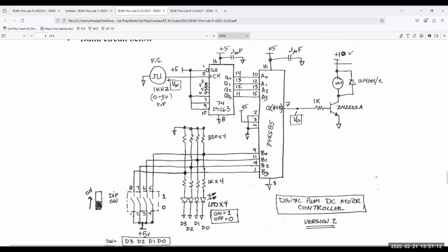We did the analog comparator. Remember in lab number 5, we did an analog comparator where you had a comparator, LM311, and you set one of the inputs using a potentiometer, right? And you set it to, let's say, in the middle of the potentiometer. That means half the resistance. Between 0 and 5, you get 2.5 volts. So 2.5 volts is set as one input, and then you had a clock counter or sine wave that was cycling through 0 and 5 volts, right?